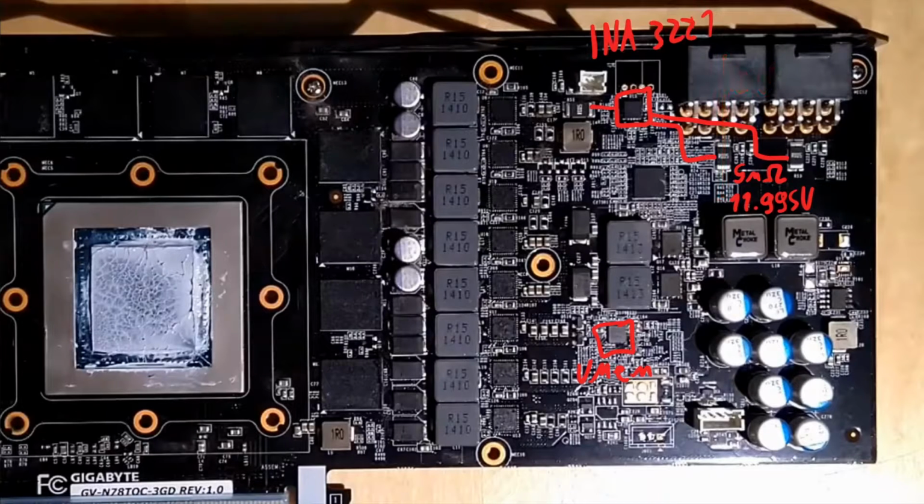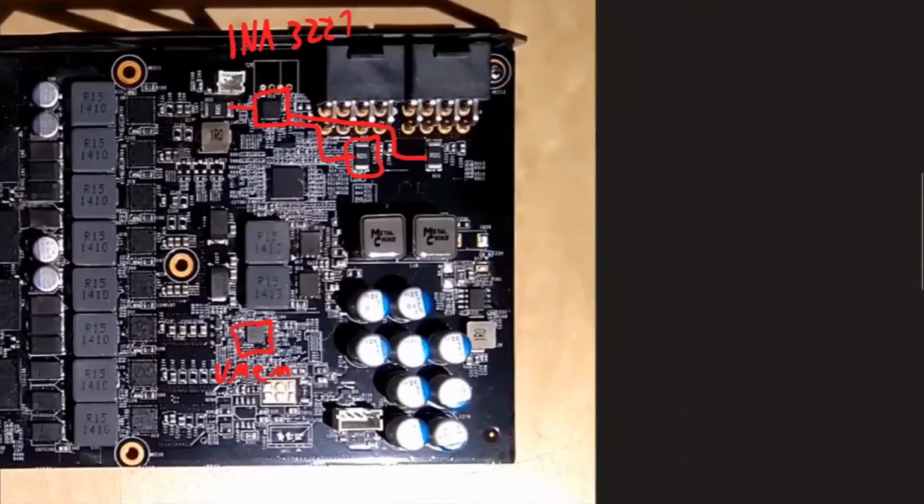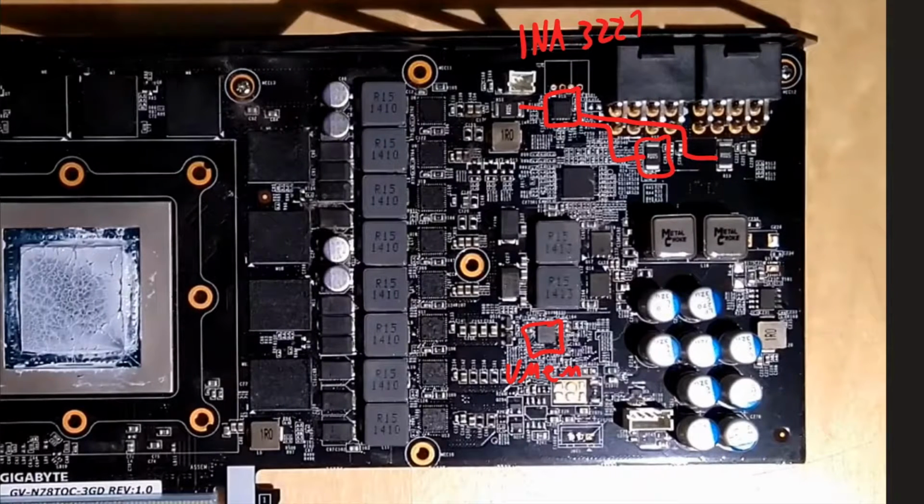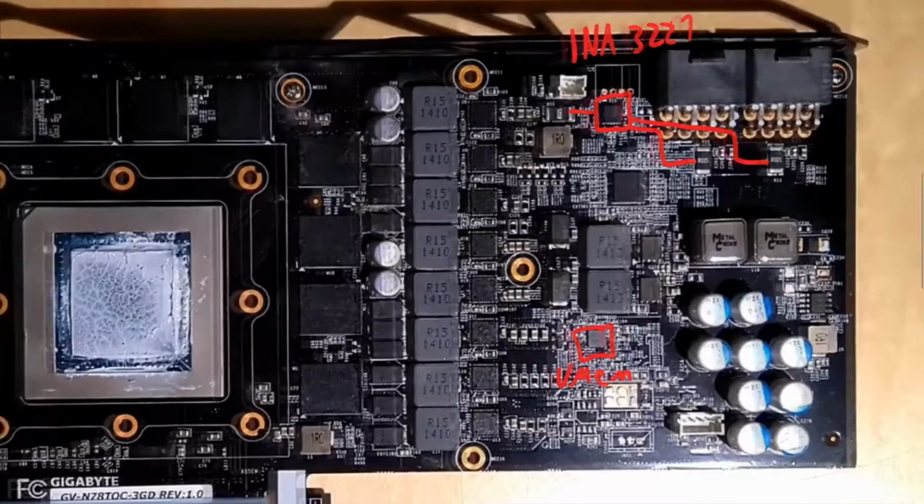It is pretty easy to trick, at least on the older cards. If you just swap that 5 milliohm shunt out by something else, if you put another 5 milliohm shunt on it, and just as before, if you put 2 resistors in parallel, you get half the resistance effectively. So out of 5 you make 2.5 milliohms, and now the card will only see half the power it is actually pulling. And that's how you can increase or totally lift your power limit on older NVIDIA cards.